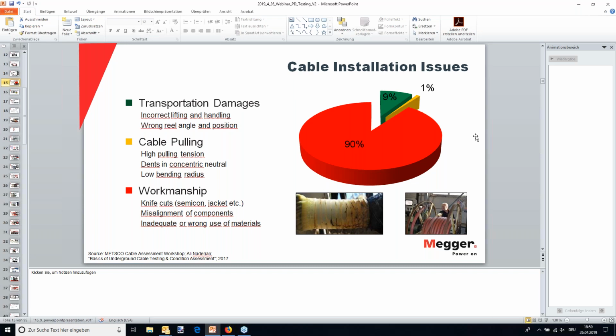On service age cables, just monitor it. Once you get activity at 1.7 and then 1.5, 1.3, keep measuring every so often. And again, accelerate based also on the importance of the feeder. An unimportant cable does not have to be tested as often as an important cable. And even an uncritical important cable should be tested much more often than maybe a medium critical cable that is not so important. Again, you want to maximize the time of the asset and find the sweet spot when to go in with your money and work some miracles.